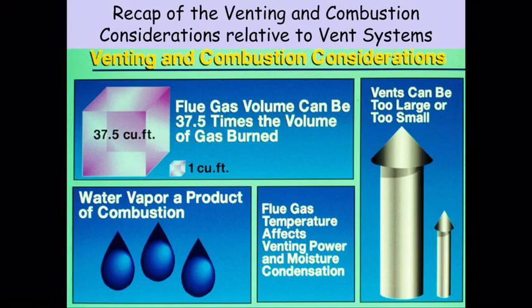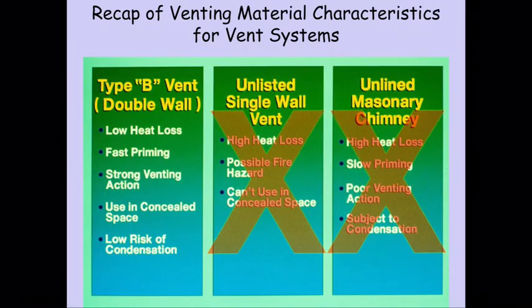Your water vapor is an issue. You've got to get your flue temps high enough in the systems to prevent that condensation. So your flue temps are a very significant factor. Your vents can be sized too large, they can be too small. Those are some things that I have to make sure of. So ultimately, I really want to appropriately size them and make sure that I'm doing my due diligence to get a system that's going to function correctly.